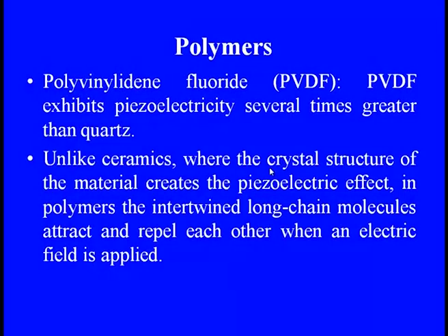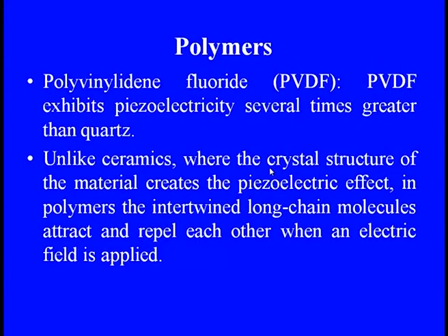Lastly, talking about polymers, till date we discussed ceramics. Among polymers, polyvinylidene fluoride, PVDF, is a perfect material which can exhibit piezoelectric crystal formation, and it has piezoelectricity several times greater than quartz. Unlike ceramics, where the crystal structure of the material creates the piezoelectric effect, these polymers have intertwined long-chain molecules which attract and repel each other whenever an electric field is applied, and they show mechanical strain. So this is a unique feature: both ceramics and polymers can exhibit piezoelectric behavior.